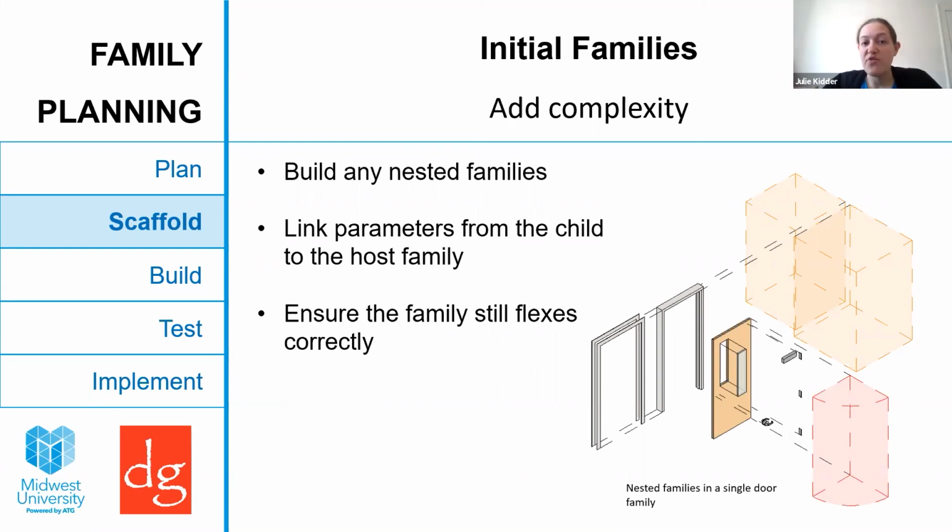So are there clearances for doors in a nested family? The clearances themselves are nested families, and they are nested in relation to the door hinge or opening, depending on the family. Everything that is nested is not meant to be placed on its own. The way we name our families is that there is an underscore at the beginning. So those families that shouldn't be placed independently sort to the bottom of any family type selection dropdown. So the doors always come with clearances built in.